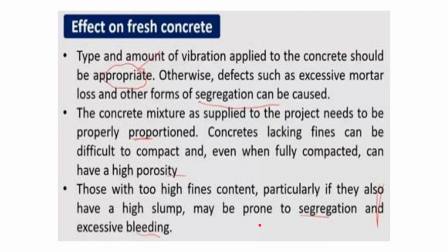So let us see what is the effect of compaction on the fresh concrete. The type and amount of vibration applied to the concrete should be appropriate. Otherwise defects such as excessive mortar loss and other forms of segregation can be caused. So therefore vibration should be appropriate. It should not be less and it should not be over either.